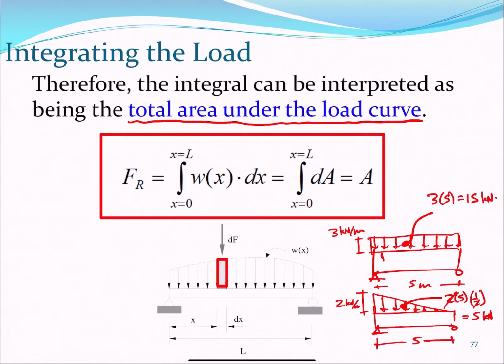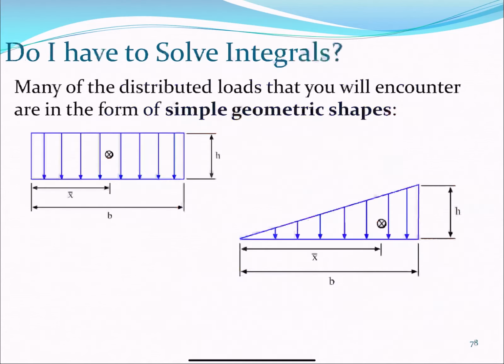So what we have to do is just calculate the area. And then we saw that the proof of that is that whatever is in the integral is the area of the load shape. Now we can calculate these loads if we know the area of basic shapes. And usually for this course, it's enough to be very good at identifying any complex shapes in terms of rectangles and triangles. Most of the problems you will be able to tackle if you just simplify the loads into rectangles and triangles.